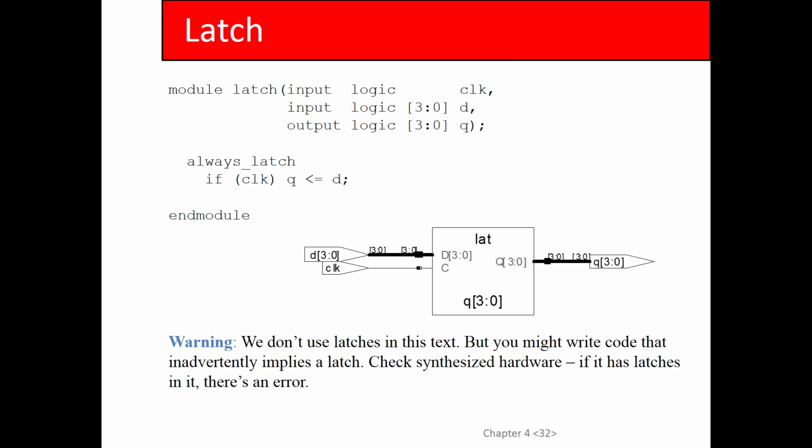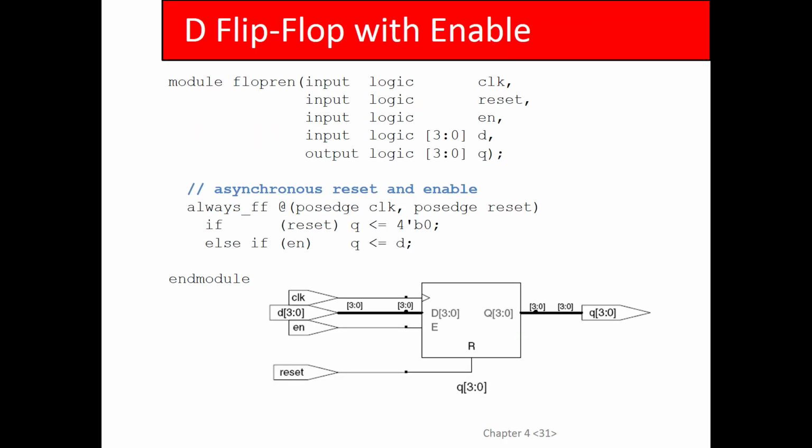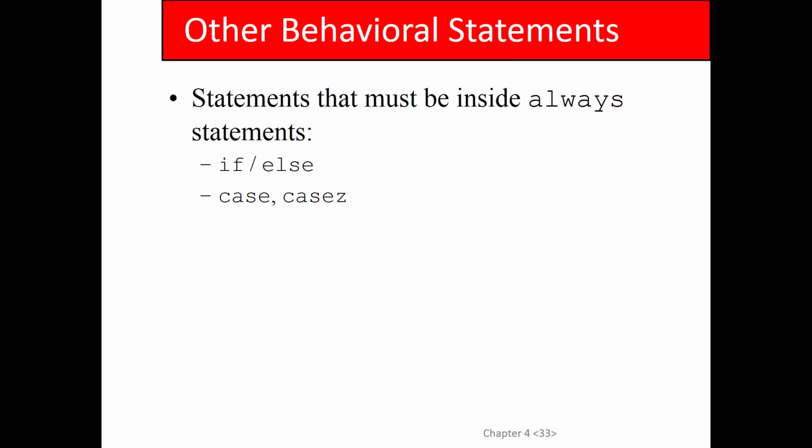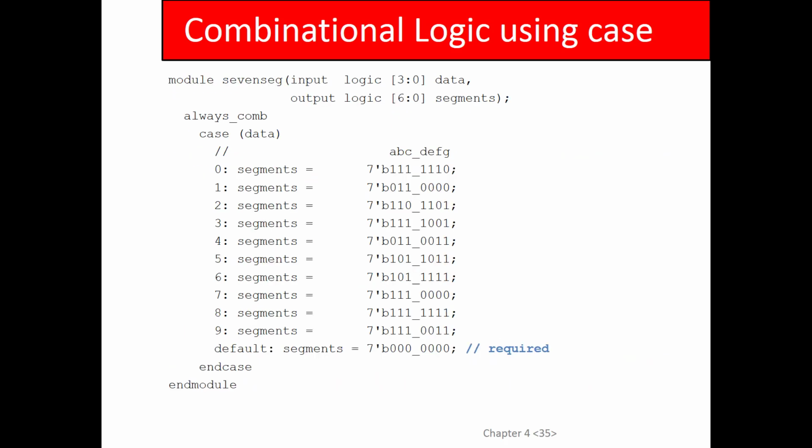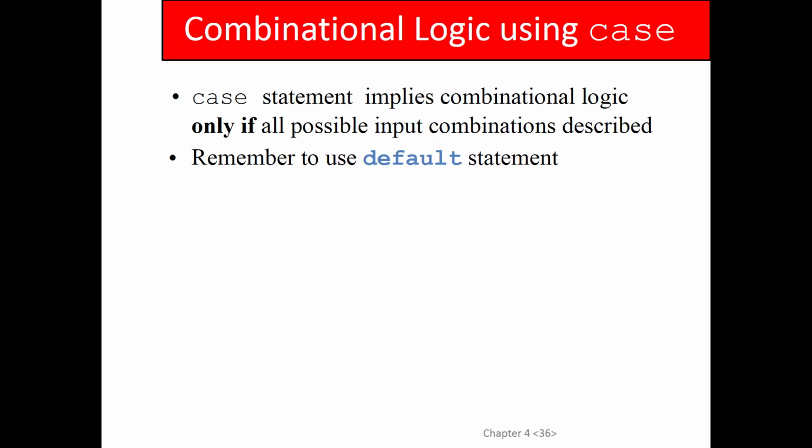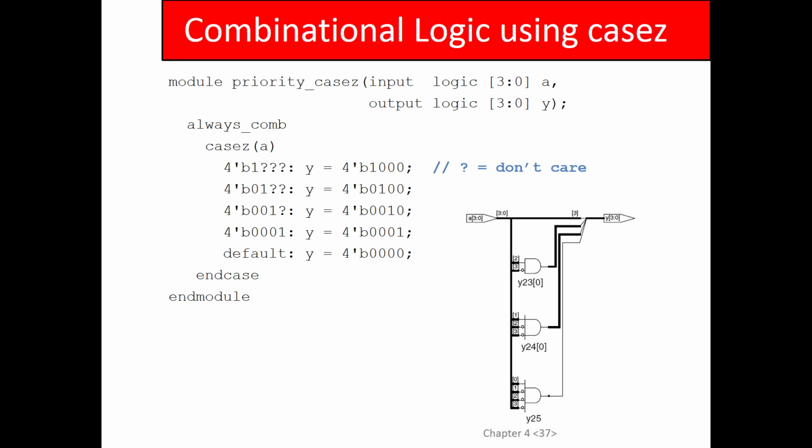Let's see here. Latches, not a big deal. You should avoid the use of latches. We covered the case statement syntax. This is really just a syntax thing you need to remember, how to build a case statement. One thing you should watch out for is there's no break in the case statement as there is in Java and C. But if you want to put multiple statements for each case, you need a begin and end. I point that out because I often forget to do that myself.